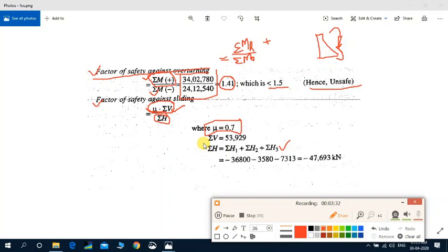In addition to that, we have to calculate the shear friction factor, wind forces, wave pressure, and other forces also, ice pressure, silt pressure. I have neglected all these minor forces. Another reason is that calculating all those forces may complicate this example, and you may not understand it well. So I have only considered the major forces. Keep that in mind.